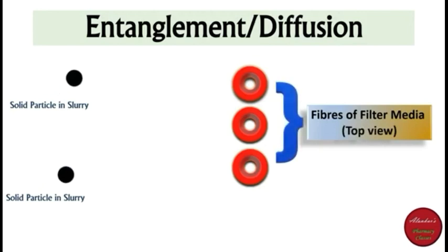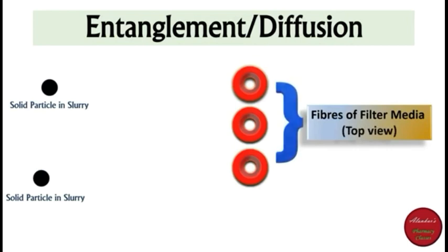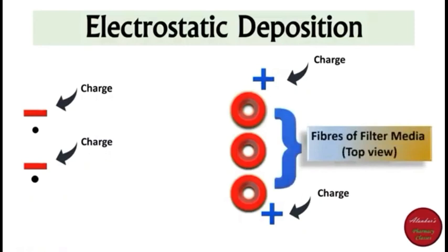Then the next is the filtration centrifuge, and it is used for obtaining anhydrous products. And the next one is the ultracentrifuge. It is used in colloidal research for separating solids from liquids, at RPM 85,000. Then next one is the angle centrifuge. Its angle is 40 to 50 degrees. And the next one is the high speed centrifuge. It works at RPM 10,000.